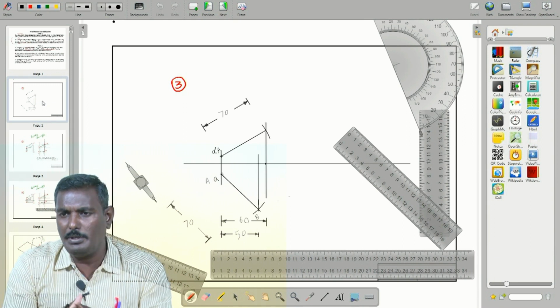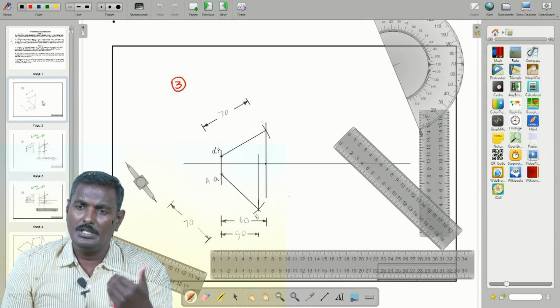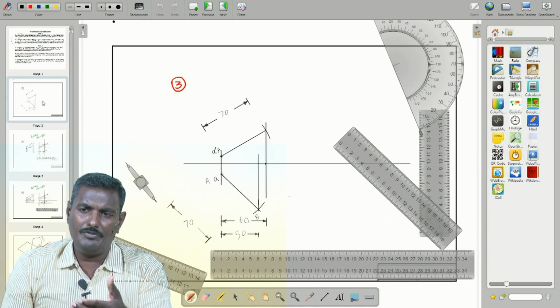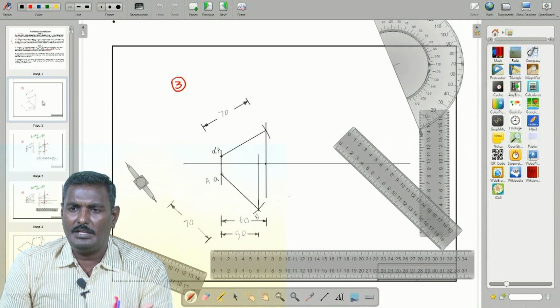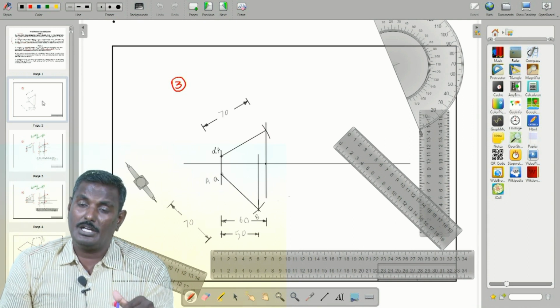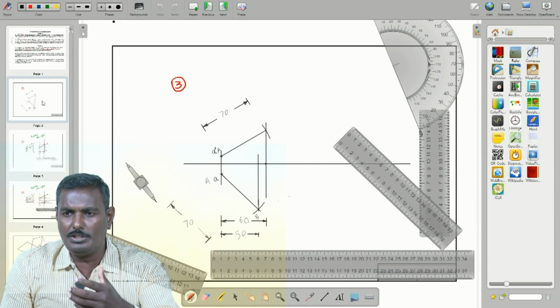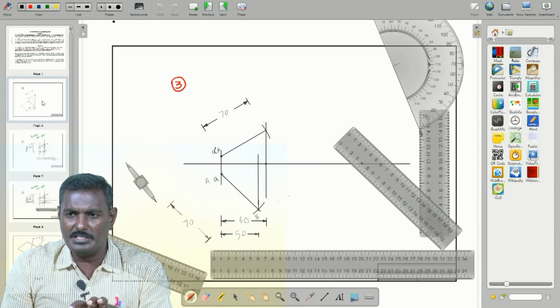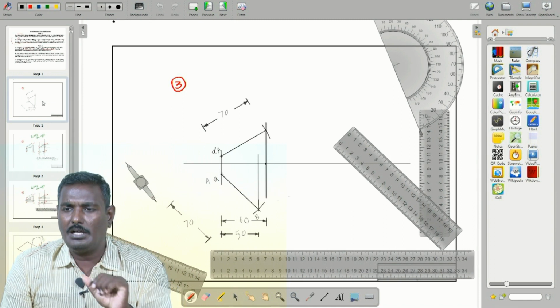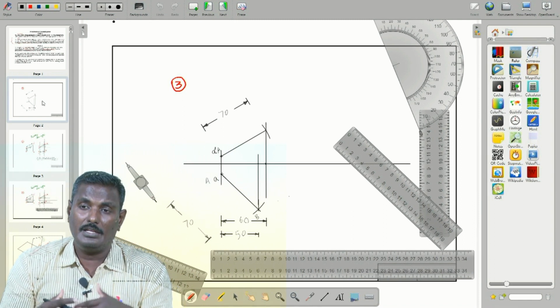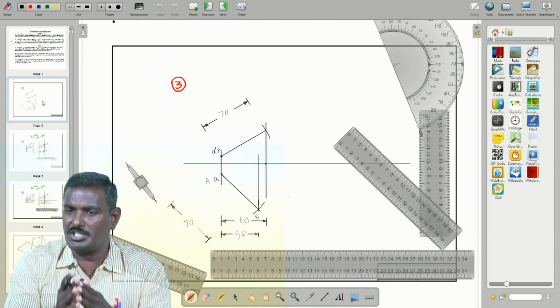What about point B? The point B dash of the elevation view and the point small b of the plan view, where? It is reverse, because by projection we determine the true length, but here the true length is given and their views are given. Individually we constructed them, and now we are making it into single projections.